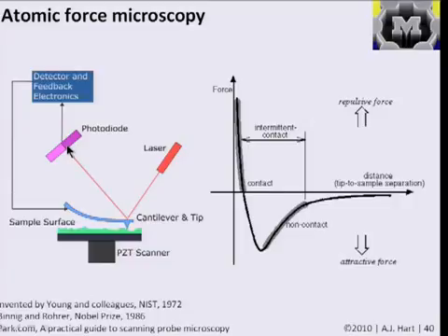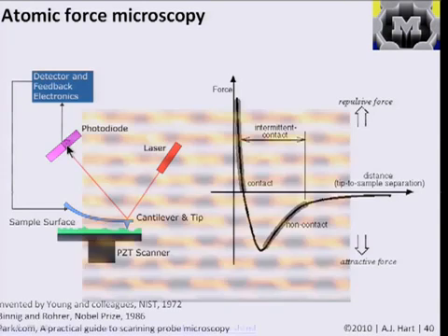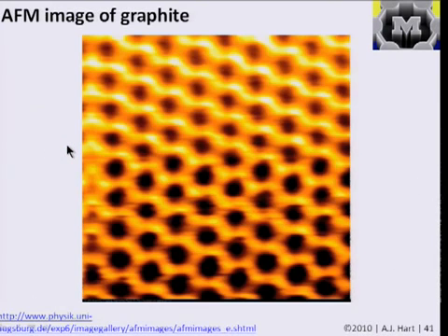So those interactions and how those interactions vary with different materials are important to really pushing the limits of this technique. But in principle, the way the instrument works is you just scan your tip across the surface, and you can take different types of images that you can with an electron microscope. Typically, a strength of AFM over an electron microscope is that, well, now AFMs operate in atmospheric pressure, so you don't need the sample to be in vacuum, and they also don't require conductivity.